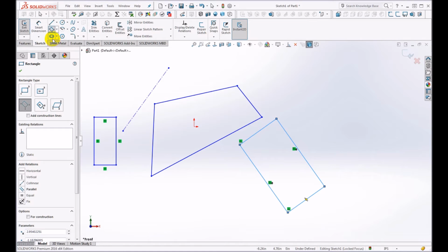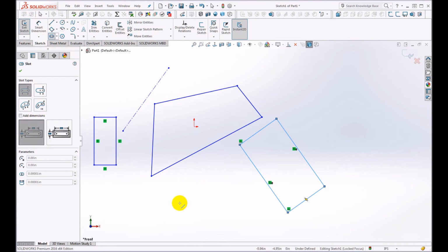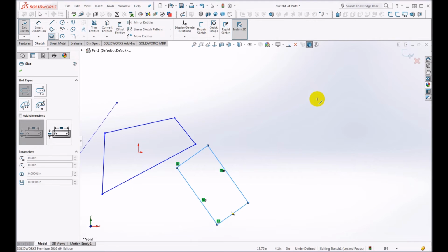If, for example, you want to create a slot for a screw, an adjustment, you could click here, and watch what happens. I'm going to go out into an open area, click once, and drag. Now I could drag horizontally or vertically or at an angle. I'm going to drag horizontally for now, and that will plant the 2 center points of the half circles.